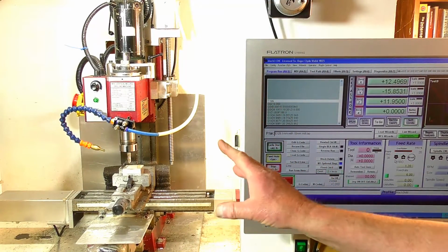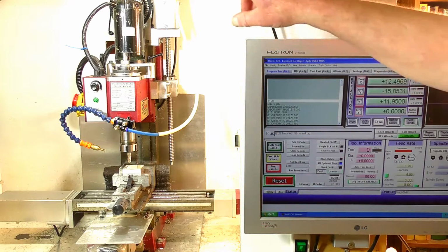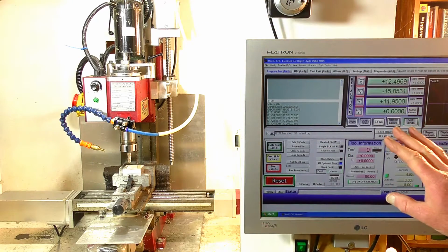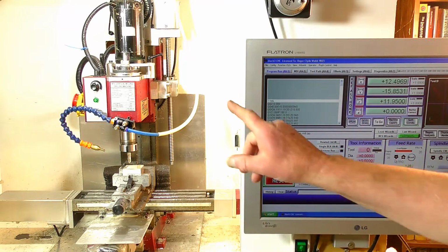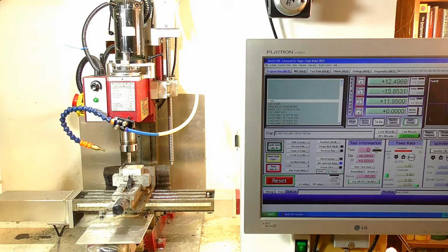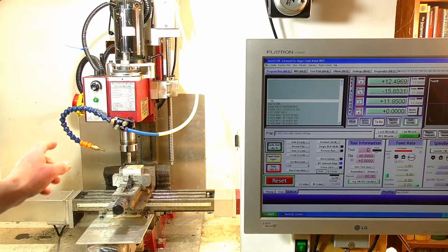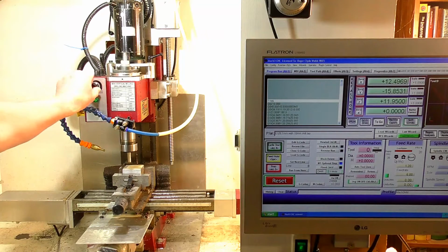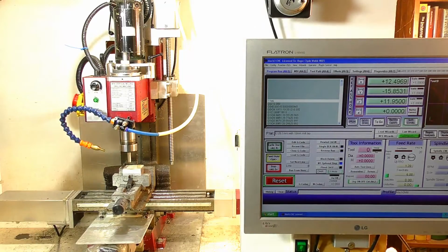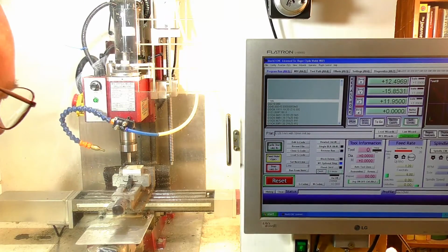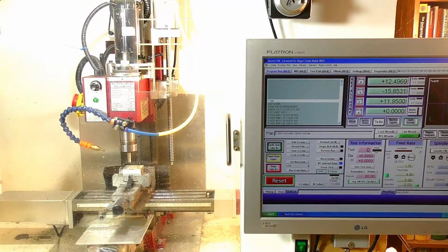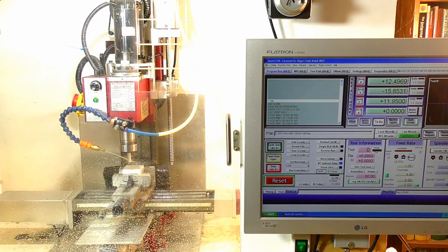Okay, so my particular CNC machine, the drive motor is not connected to Mach3. It's not controlled by Mach3. So I have to start that up manually, separately. And also I should be running flood coolant, so I'm going to be shutting all these doors. So we'll start the spindle up first. As you can see, it's spraying all over the place.